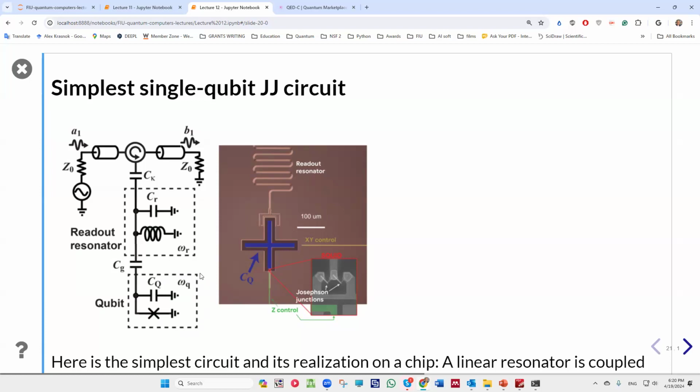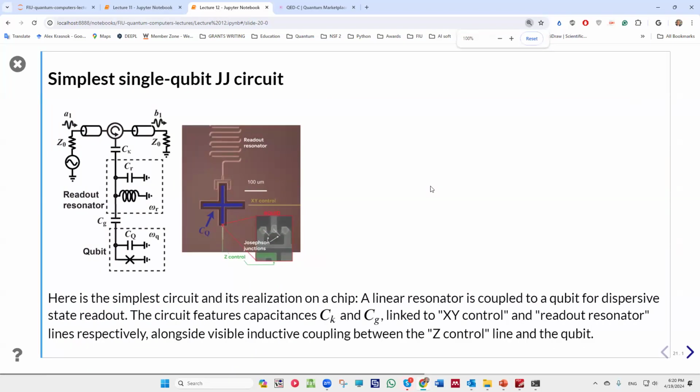So this is my Josephson junction based qubit. Over here, I capacitively couple this junction, this qubit, to the readout filter, readout resonator, like shown here. And then through a circulator, I can excite and read out this qubit in my circuit. So essentially, it is all about microwave engineering, electrical engineering.